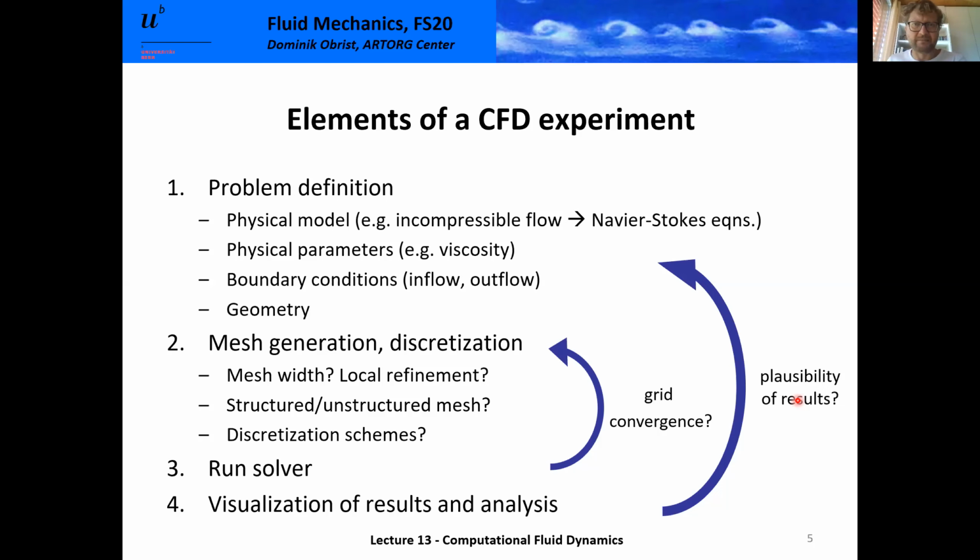There are cases, and maybe if we have the time, we'll get to that today, where the solver tells you, this is the solution, I believe, that is the correct solution of your problem. But if you check for plausibility, if you do certain order of magnitude calculations with the background information you have, if you compare Reynolds numbers and typical results, let's say for canonical flows, like flow around a cylinder, and you see, well, this result probably cannot be true, then you need to go back.